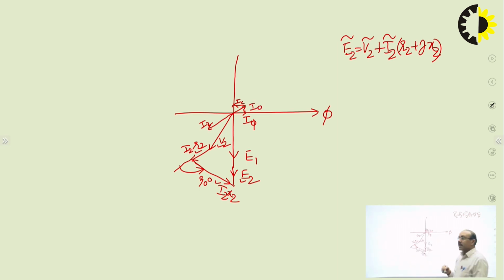That we have already discussed in the previous case, when we discussed the transformer phasor diagram at no load condition. Now, due to the current I2 in the secondary, the primary winding draws additional primary current, that is I1 dash, which is known as the load component of primary current, as we discussed in the previous slide, and that is in anti-phase with I2, or in phasor opposition to I2.